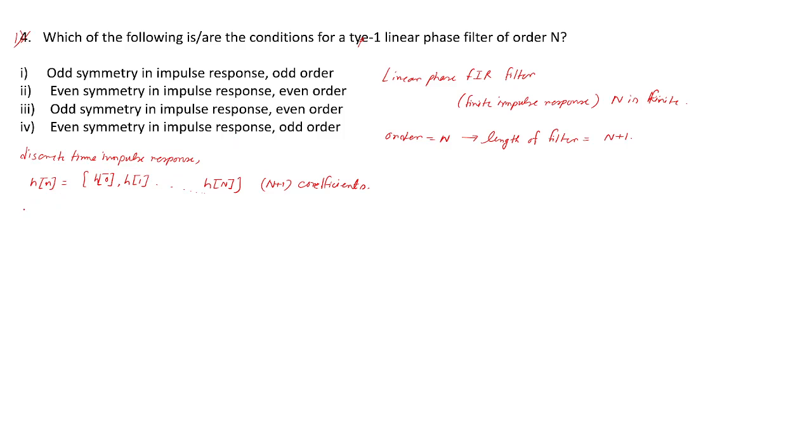And if we take the Z transform of this h[n], earlier in problem solving sessions we saw that n runs from minus infinity to infinity, but since it's a practical causal filter, this arrow indicates the position of the 0th index. Your n no more spans from minus infinity to infinity. It starts at 0 and ends at N. The rest of the things remain the same.